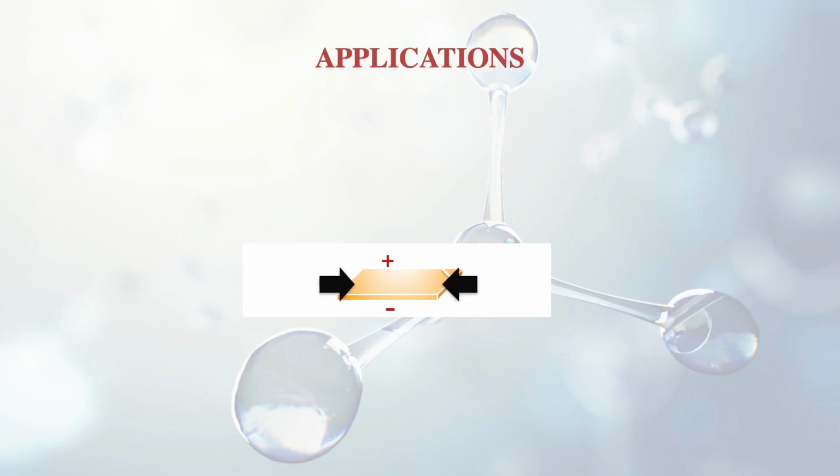Energy harvesting means this piezo element can serve as a generator. In fact, it's a very compact generator with no moving parts, and it can produce electricity in this fashion if it is under dynamic stresses. Now, as far as the converse effect is concerned, piezo elements are used in mobile phones, the speaker which converts electrical pulses to sound waves. They are used in fuel injectors, musical cards, inkjet printers, vibration control, turbo machinery, numerous kinds of actuators, and precision positioning.